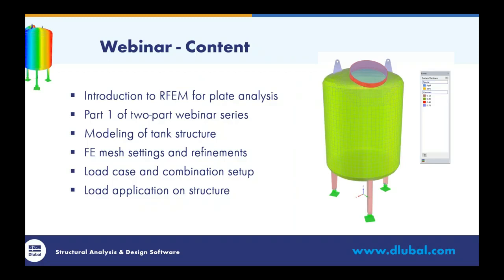So regarding the content for the next hour today, this will be an introduction into our finite element analysis program, RFEM, for plate and shell modeling. This is part one of a two-part webinar series. Today, we're really going to be focusing only on the modeling of the tank structure, which you can see on the right-hand side. We're going to discuss certain aspects such as the FE mesh settings and mesh refinements. We will set up our load cases as well as our load combinations per the ASCE 7. And finally, we will apply the loads to the structure.